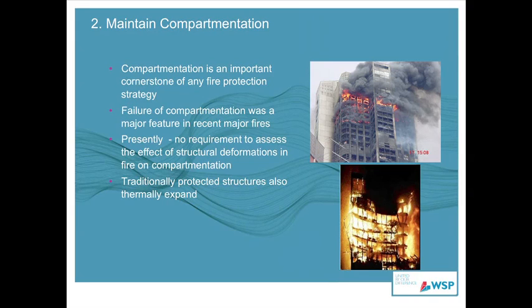Also, we have other elements of the structure which are not protected at all, like the slabs, and they will see the same thermal regime whether the structure is protected or unprotected. What they will see is a different strain response within themselves, whether they are protected or unprotected. That is clear. So the use of advanced tools is really the only way of actually trying to understand how a particular floor plate would actually behave when it's subjected to a severe fire.